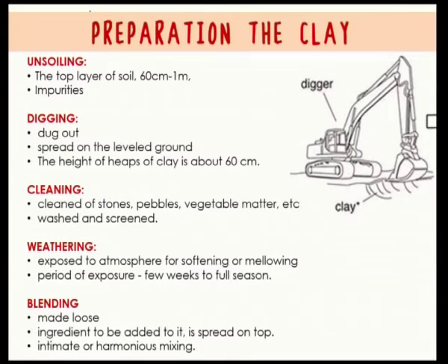This can be done manually, and nowadays a lot of machinery is also used to dig out the clay. Now, once the clay is dug out, it is spread onto a leveled ground and put in heaps. These heaps should be of about 60 centimeter height. Next is cleaning the clay.